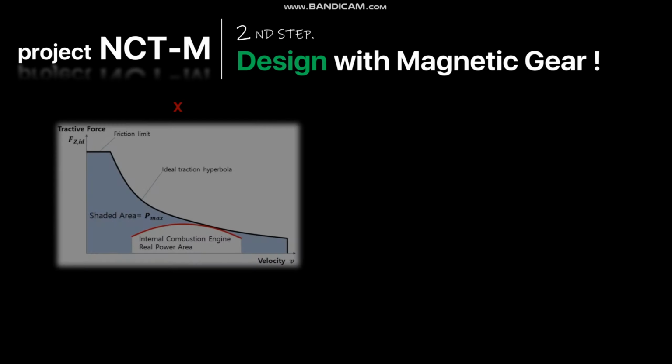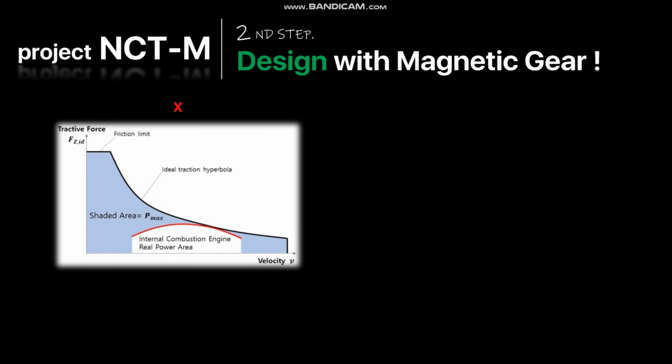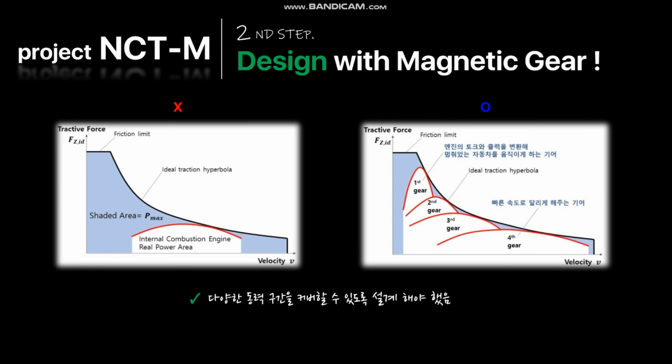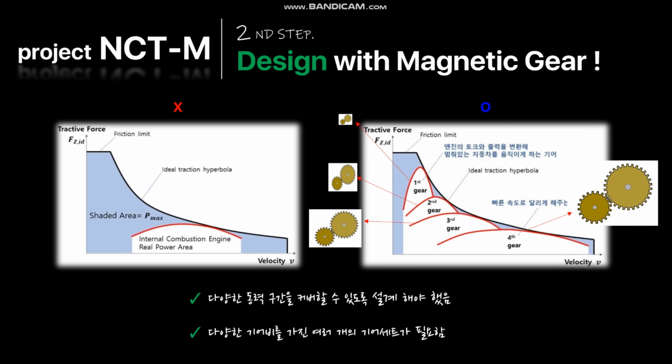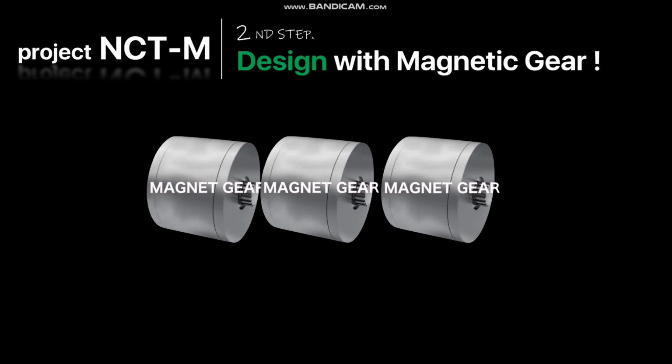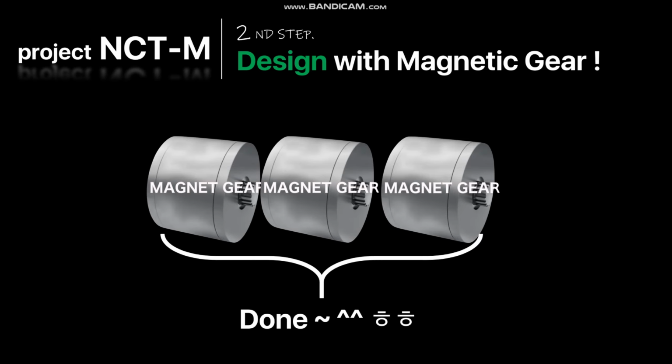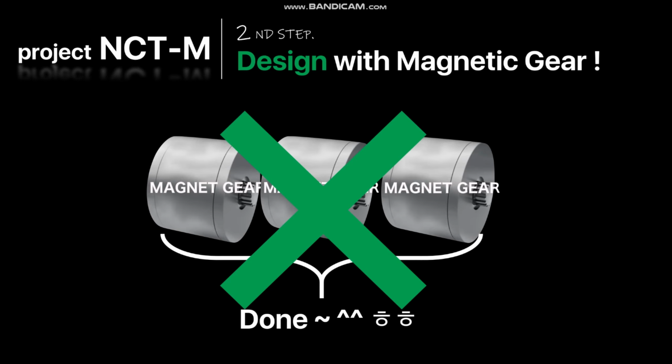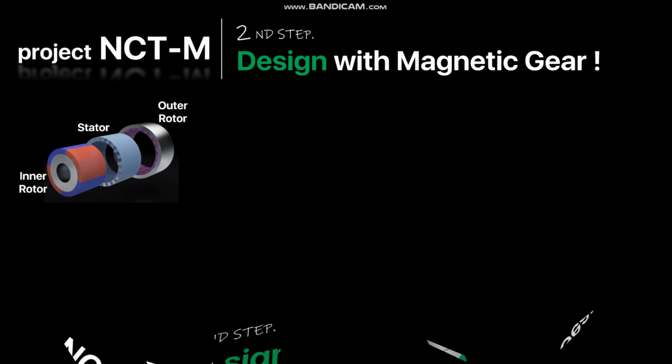Second step is designing with magnetic gear. To cover a wide range of velocity area, multiple gear sets with different gear ratios are essential. So we need multiple magnetic gear sets. So let's prepare 3 pairs of magnetic gears and connect them in a row. Done. But our goal was making the system in a compact size and in an efficient way. For this goal, we redesigned all parts of the magnetic gear from the bottom.